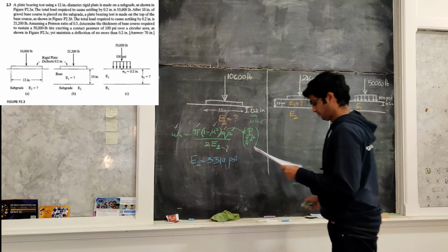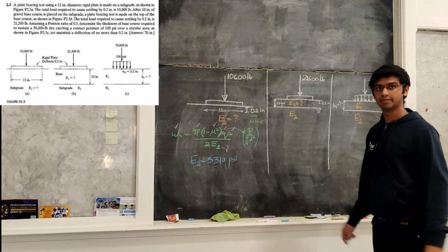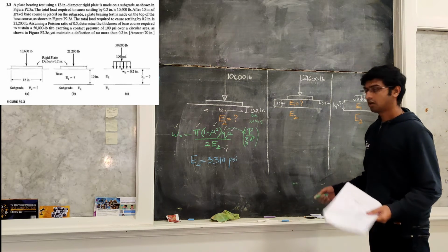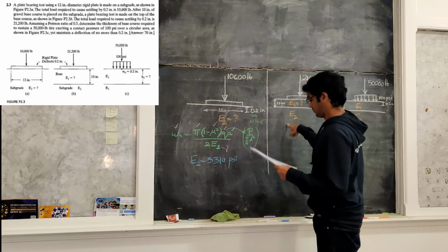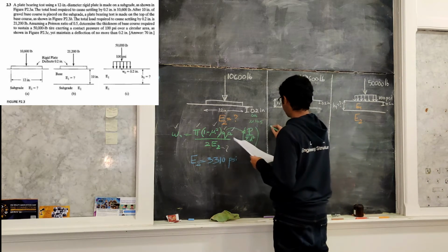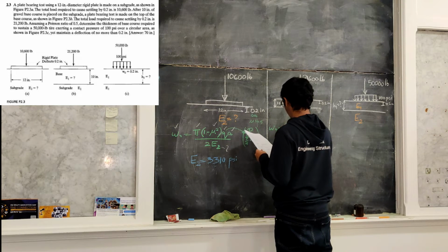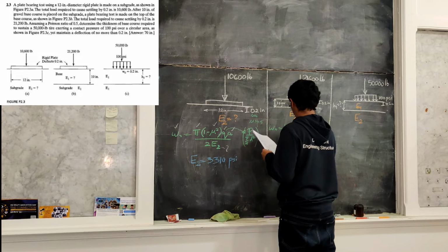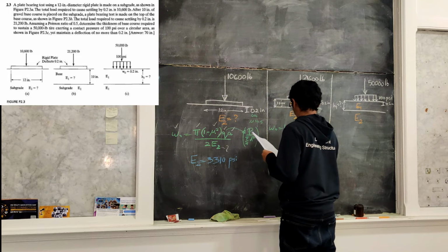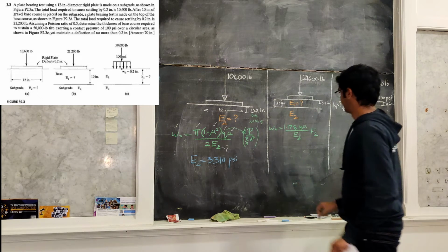In case 2, now we have 2 layers. With 2 layers, we need to use Burmister's theory, or we can use Burmister's charts. Again, for the deflection, W0 is 1.178 QA by E2 times F2.